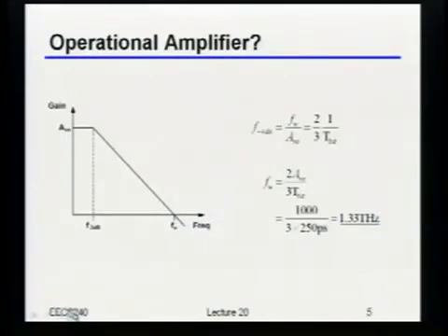So, if I wanted a comparator, I want this gain, I want a bandwidth, I should say, okay, fine. Why don't I just build an OTA? The standard way we talked about. I'll just take some transistor, tie it up to an amplifier. I can get a gain of 1,000, right? And so maybe I can get enough bandwidth. Let's see if this actually works.